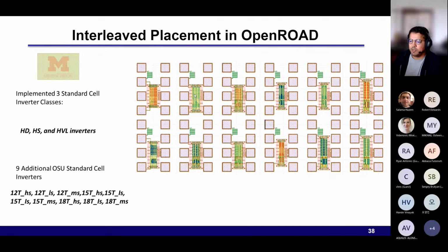So we have done this for multiple VTs in the SkyWater PDK. So there's 3, 1, 2, 3, plus 9, so basically 12 standard cell libraries, and different versions of the ring oscillator as well. You can see here, these are all automated and can be used for process variability as well, or process centering monitors.